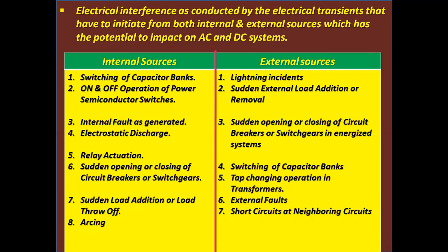And the external sources: that is lightning incidents, sudden external load addition or removal, sudden opening or closing of circuit breakers or switch gears in energized systems, switching of capacitor banks, tap changing operation in transformers, external faults, and the last one, short circuits at neighboring circuits.